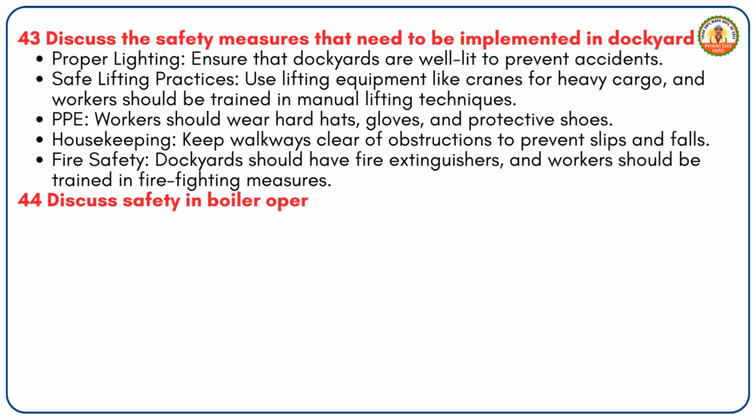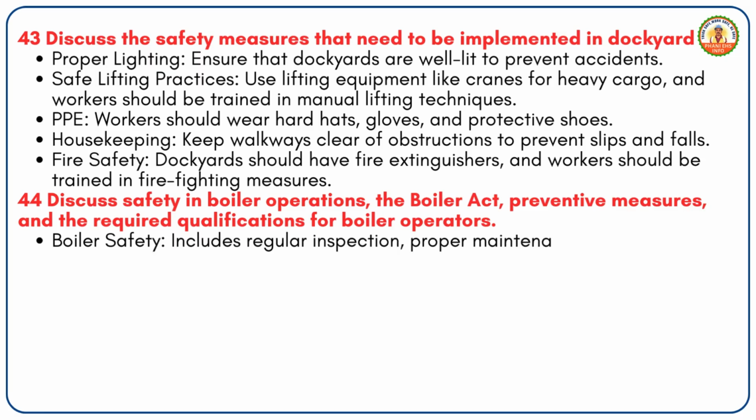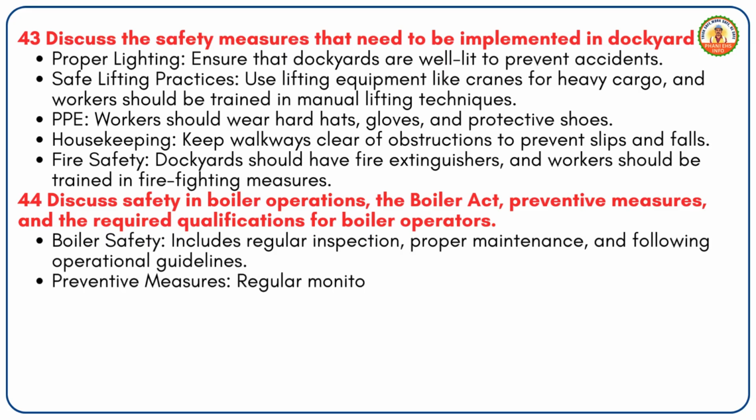44. Discuss safety in boiler operations, the Boiler Act, preventive measures, and the required qualifications for boiler operators. Boiler safety includes regular inspection, proper maintenance, and following operational guidelines. Preventive measures: regular monitoring of pressure levels, temperature, and water levels.